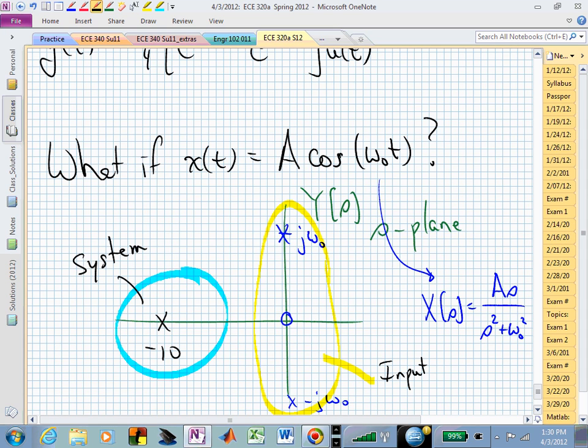And what do we know about those two poles on the imaginary axis? Do they have any decay associated with them? Is there an e to the minus something t? There is, it's just that something is 0, right? E to the 0 t. So there is no damping associated with those. They're right on the imaginary axis.